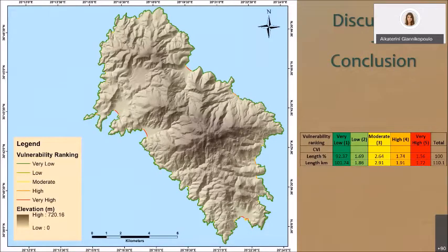In the final map, the red color highlights areas where the various effects of sea level rise may be the greatest, taking into account that physical process variables and shoreline erosion and accretion rates are the same for the whole island. Those that effectively determine the CVI are slope values and geomorphology. Overall, we can see that the vulnerability is unevenly distributed among the 5 risk categories, with low risk prevailing for the most part of the island's coastline. The very high vulnerability ranking characterizes locations of small slopes and sandy pocket beaches.